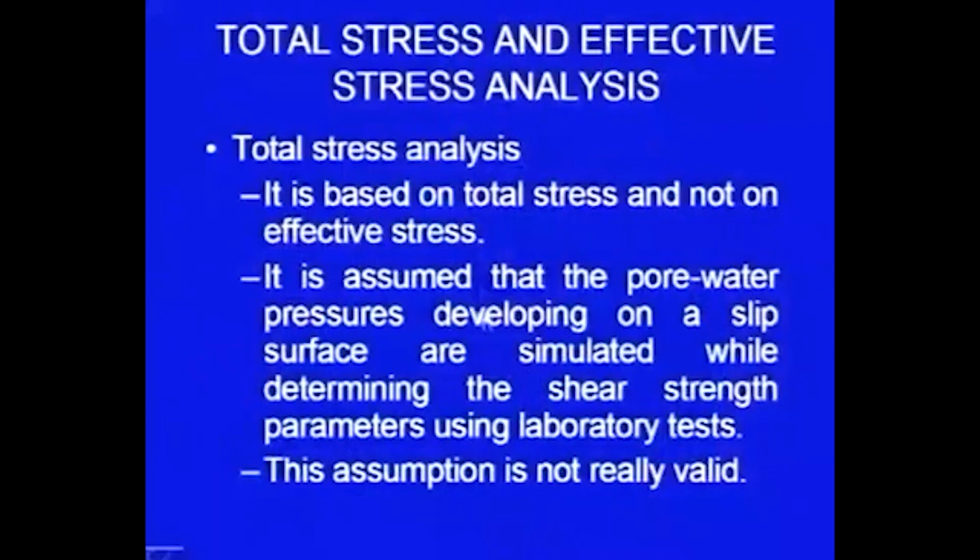It is assumed that the pore water pressures developing on a slip surface are simulated while determining the shear strength parameters using laboratory tests. Our assumption in this case is that when we did the laboratory test to determine the shear strength parameters, all those conditions of the pore water pressure were properly simulated. This is our assumption, that in the test itself pore water pressure was there, but unfortunately this assumption is not really valid. So, we have to keep it in mind.